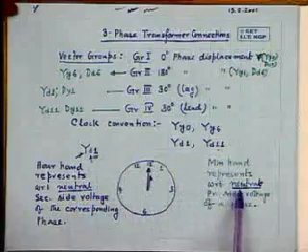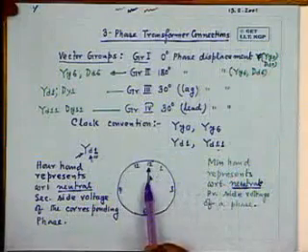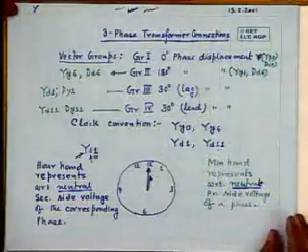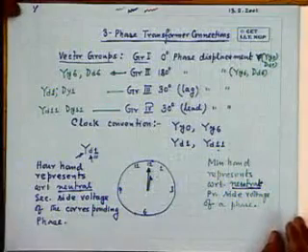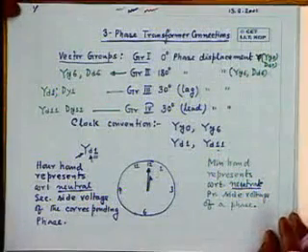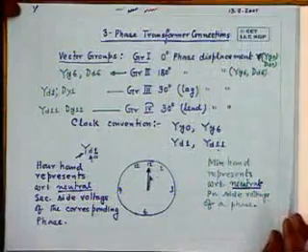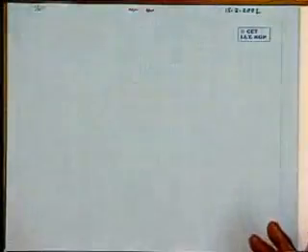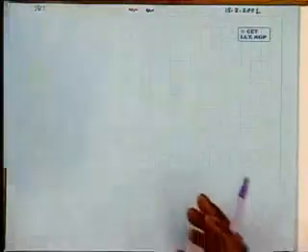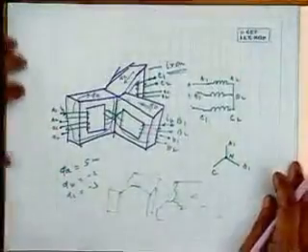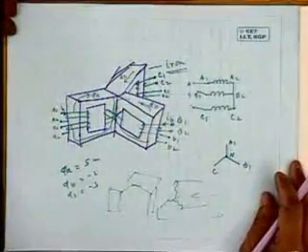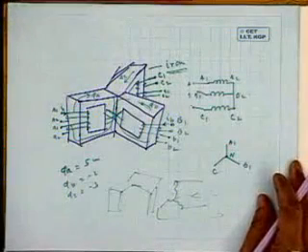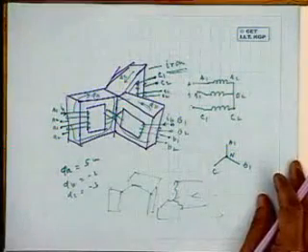And all these voltages, this angle, lead or lag, will be described with respect to neutral of the respective side. Even if the side is delta connected, we should consider the neutral, that is the artificial neutral with respect to that. So that we described in detail. Now after that, what I told is that 3 single phase transformers can be connected as a 3-phase transformer, and you can transform a 3-phase voltage from one level to another nicely, no problem.